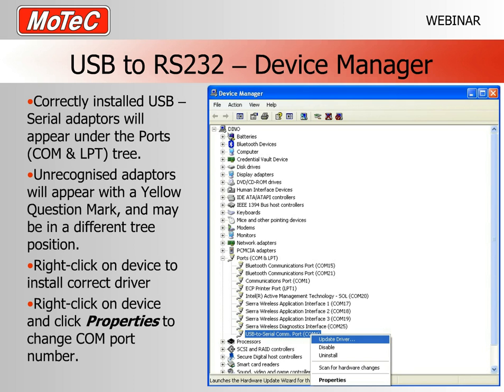Okay, now what I mentioned was that we tend to want to use low COM port numbers. If you do an automatic install, there's a high chance it's going to be a very high COM port number, and the reason, as you can see, this is on the typical laptop here, we have a lot of COM ports which have been assigned to things like Bluetooth, to the various wireless applications and so forth, and some of these applications use 3 or 4 COM ports each. So they will be assigned automatically, and they will just chew up all of your low numbered COM ports. So therefore we get this one appearing, and it may end up being COM26 or something like that.